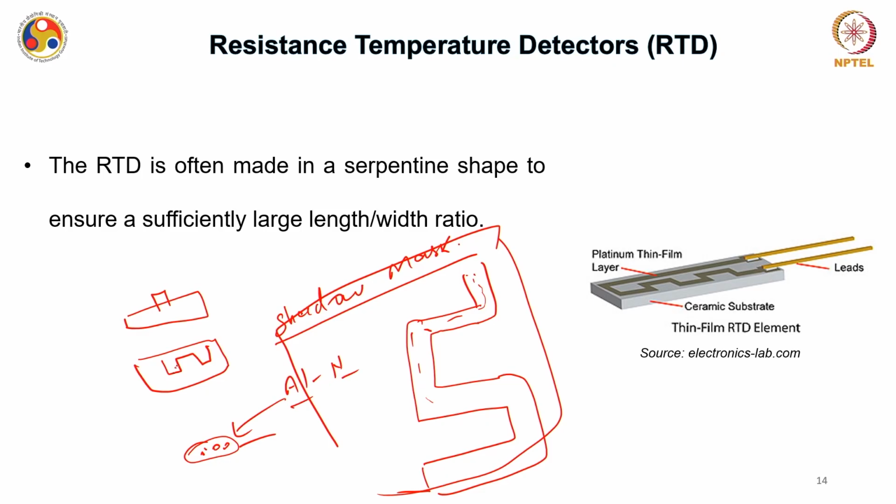By just evaporating and using this, you will have exactly the pattern transferred on your wafer. Okay, this is a very crude technique for deposition, but more scientifically proven techniques are in the form of lithography. You have photolithography to fabricate this kind of devices. There also you should have a hard mask, and there we use the concept of photoresist.